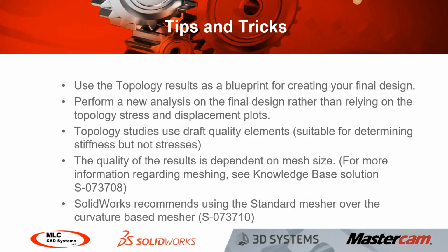And then use the topology results as a blueprint for creating your final design, meaning you do need to create that final design to run your study. So don't rely on the topology stress and displacement plots. You've got to run your analysis on your final design to ensure it's going to meet design requirements.